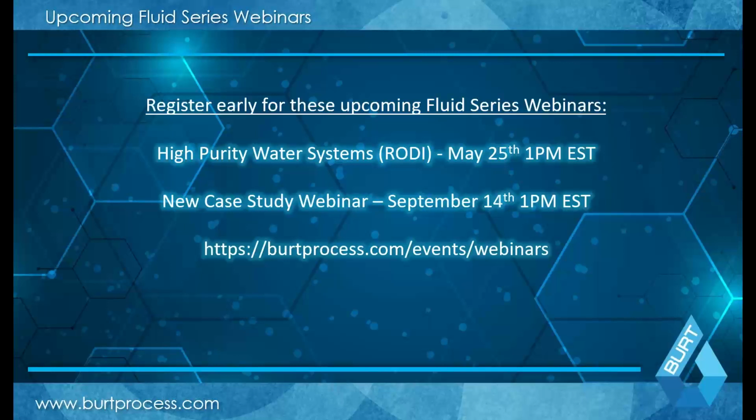If I have 50 GPM and a pH of 2, I can calculate the level of acid present at that flow rate, and the amount of caustic you need to adjust that, as a basic model. When other considerations come into play, like alkalinity and water quality data, it can get a little more complicated to calculate an exact pinpoint amount, but it can be modeled in those cases.